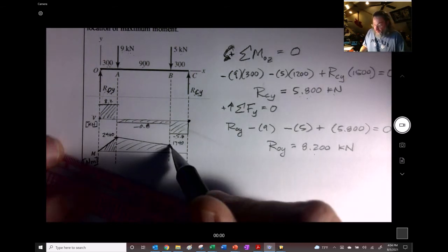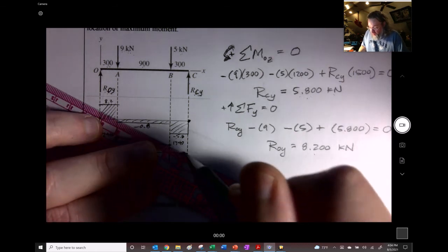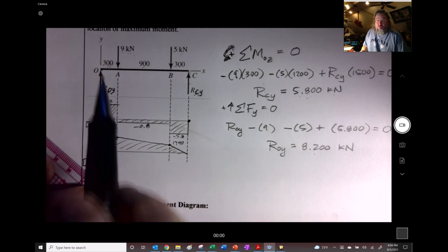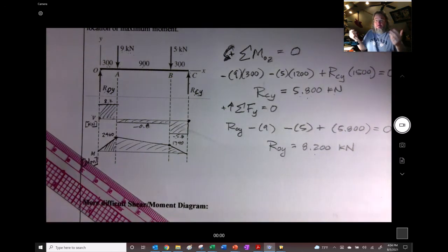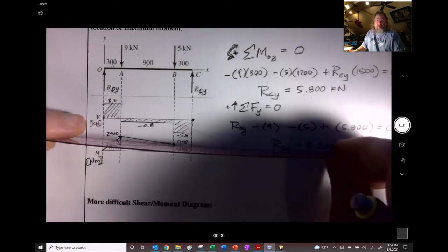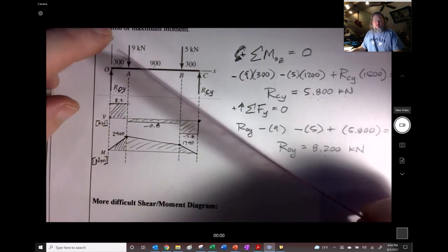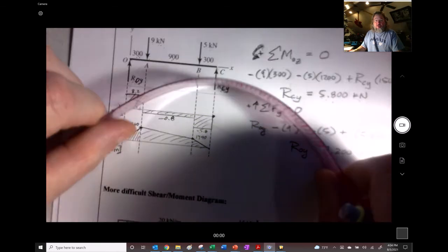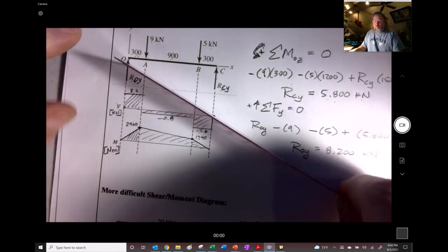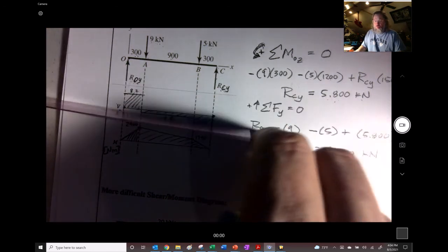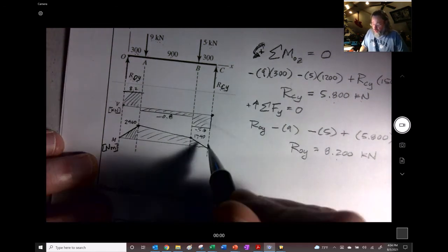Now this next part of it needs to go back to 0. And you go, why is that? Because these are pinned joints, these simply supported joints, and they don't support a moment. It's just free to flex. Like if this was right here, it would be free to flex. This would be like pinned right here, and it's allowed to bend as much as it wants to at this place right there. So these joints don't support a moment, so it has to be 0.